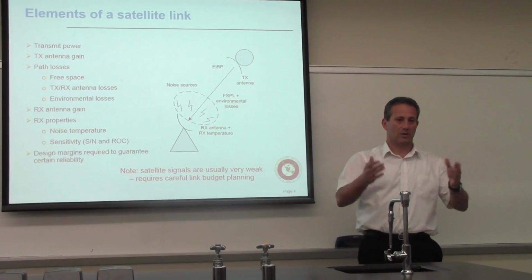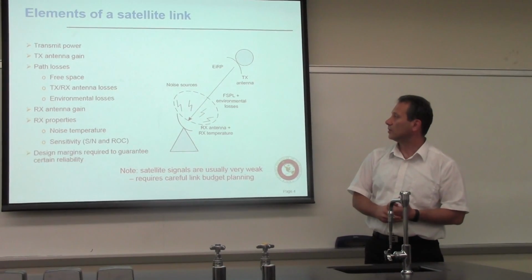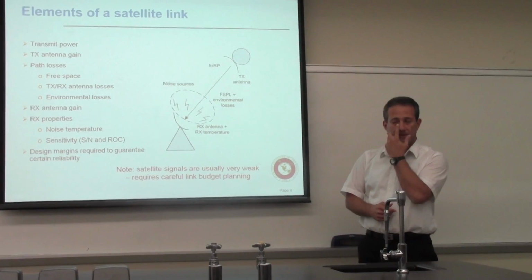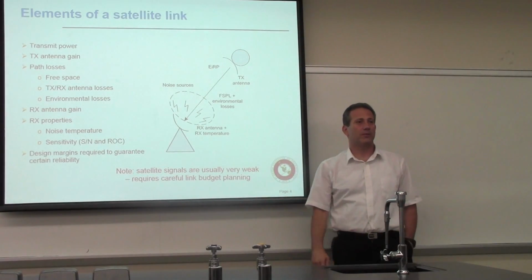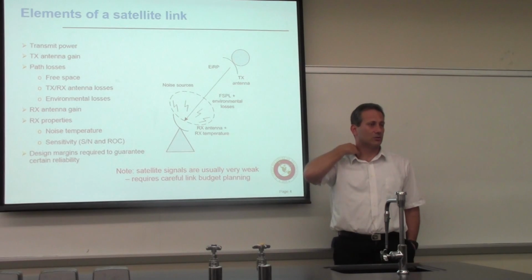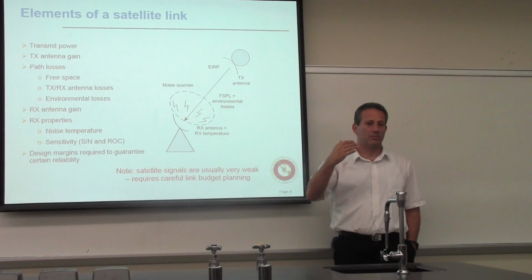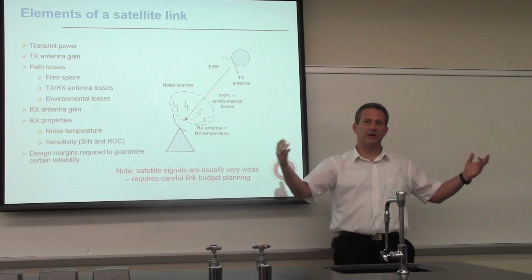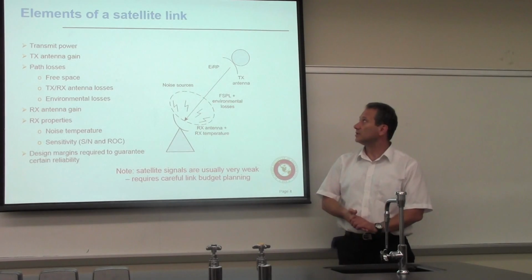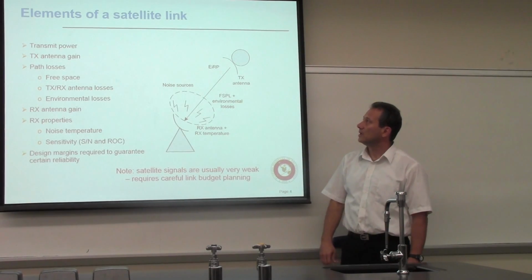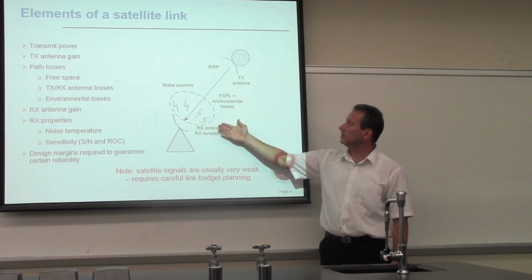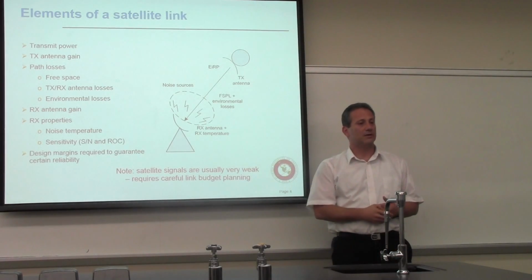You have to obey certain limits of your satellite spectrum. But on the other end, you have a satellite, which is powered by solar arrays, and those solar arrays are not powering a single transponder. There's a bank of transponders, so there's a limit on the power on the downlink, and you have to take that into account.